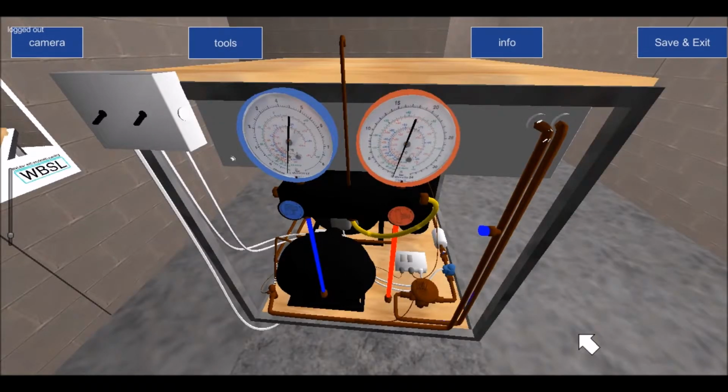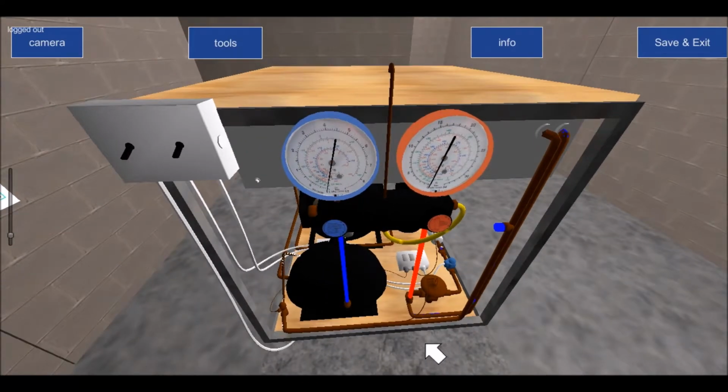So what that means is, because this is a training rig, we don't have a room stat fitted to it. We just have a typical on-off switch to give a power on or power off, and we have a solenoid on-off switch to energize or de-energize the solenoid.